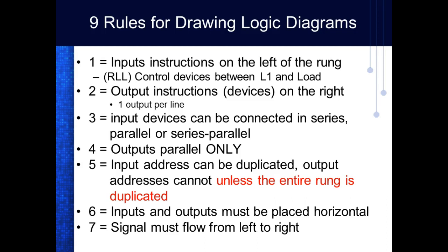But we had somebody do it last lab. What happened is they had two of them working off a switch, but they used the same address. Didn't get an error, compiled no problem, downloaded it into the PLC, but it didn't work right. It worked like an AND. So this switch and this switch had to become true, because if this instruction was false and this was true, right, understand, it took it as being false. So both had to be turned on before the actual true output turned on. So you got to be real careful.